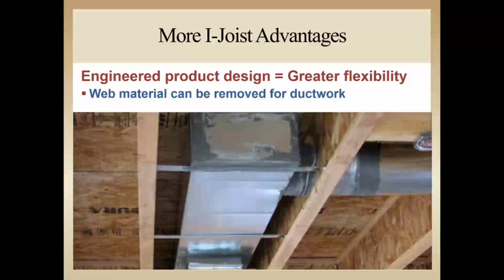As shown in this picture, the ability to cut appropriately sized and positioned holes in I-joists facilitates the running of ductwork perpendicular to the joist, and the possibility of increasing the spacing between the joists allows larger ductwork to run between them. These opportunities are maximized with the cooperation of the floor designer and, of course, the HVAC contractor.